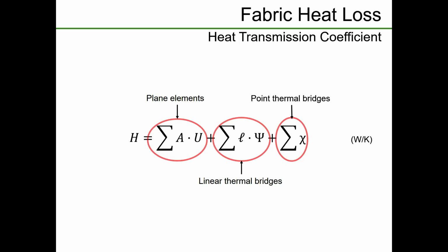By and large, the point thermal bridging gets ignored in energy assessments. For some reason, building regulations don't seem to be that interested in it. Not quite sure why. I think it's because we're still grappling with this part, that this is an additional complexity. However, where these cause excessive bridging, and there's a potential for moisture risk, then they should be assessed to ascertain whether they will cause that risk or not.